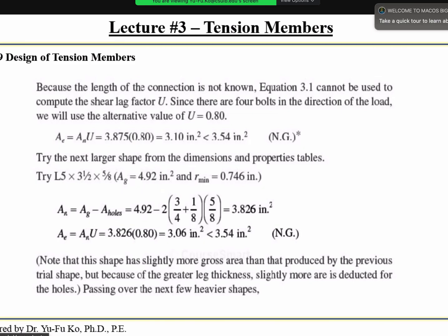As long as you remember, you need to pick the minimum radius of gyration, I think that will be fine. If we just pick the minimum, then we should be good. But if it is symmetric, we're not going to pick RZZ. There's no RZZ for symmetric, only X and Y. And then we pick the minimum from those two, correct? Yes, yes.